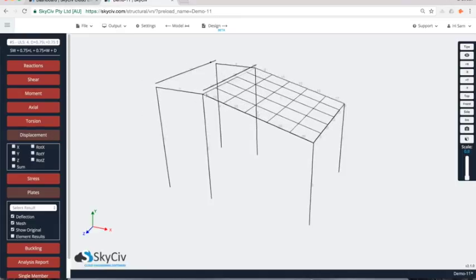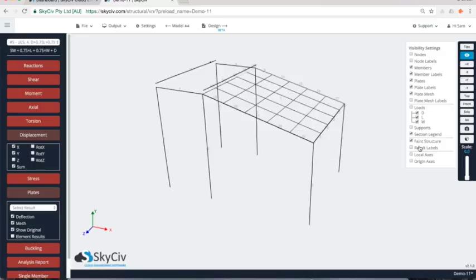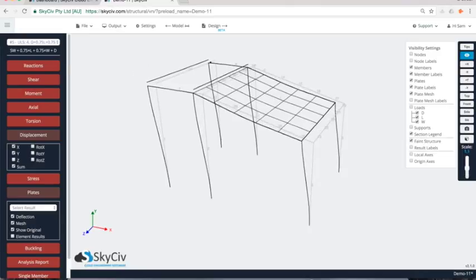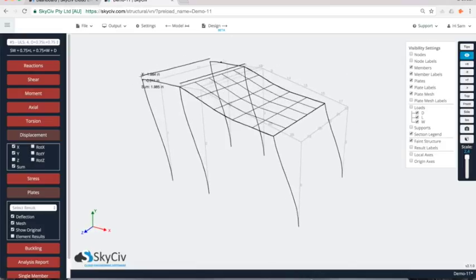You can also hover over the areas, so for instance displacement, if I turn these results on, and I can also turn these results off here, so maybe I don't want to look at the result labels, but I can still hover over here and look at what's happening there. And so I've got a cleaner diagram, especially when I start to deflect it, and then I can notice, all right, well that might be an area of concern in terms of how much that node's deflecting, and I can review that independently. And again, might be a good opportunity to take a screenshot.